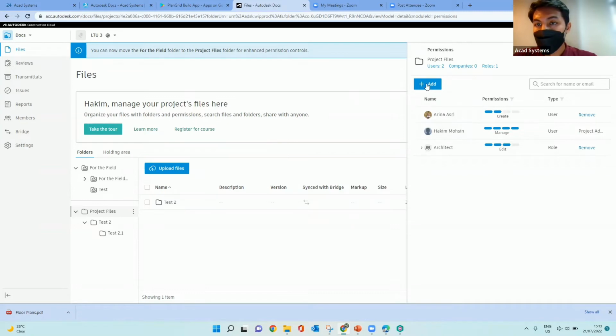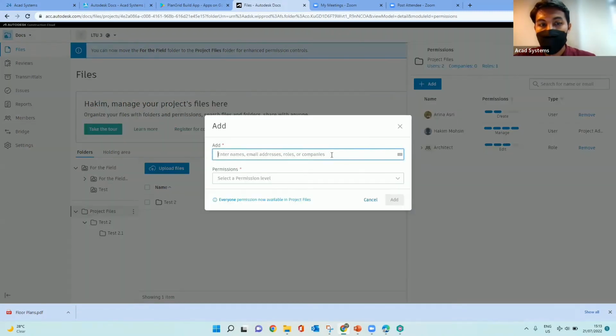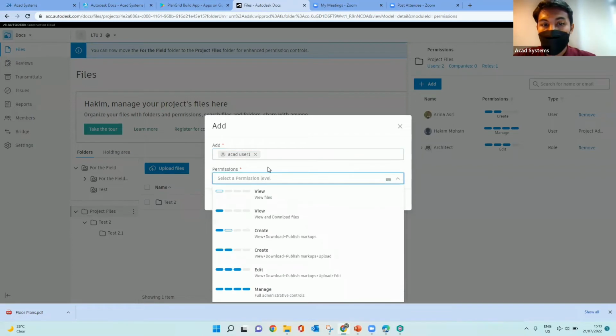So how do I add, for example, another person? I will just click add here, and then I need to enter the name. These people you should first add as a project member. If you don't know about that, you can check out my previous video on how to get started in ACC. So you add the person, and then at the permission, you need to select one of the permission levels.